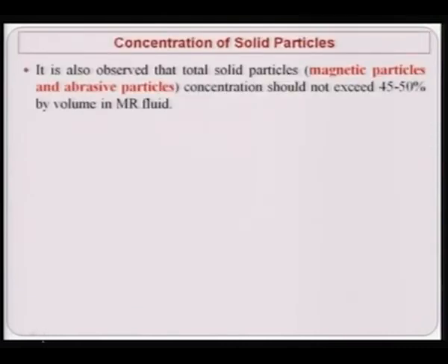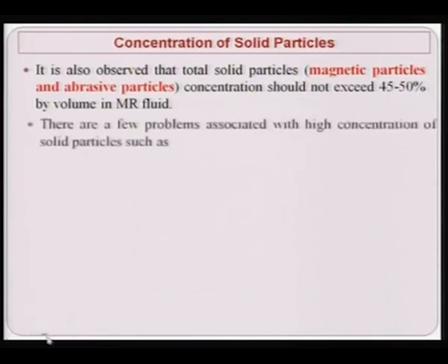Concentration of solid particles: it is also observed that the total solid particles, that is magnetic particles and abrasive particles, concentration should not exceed 45 to 50% by volume in MR fluid.